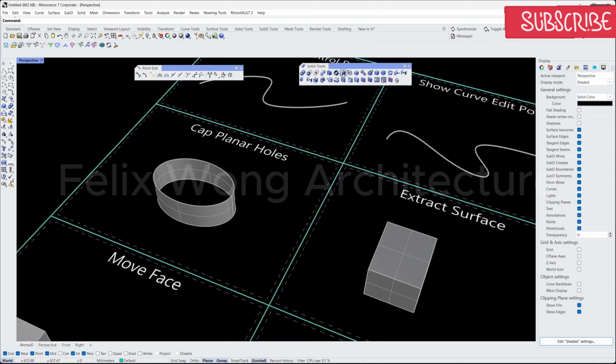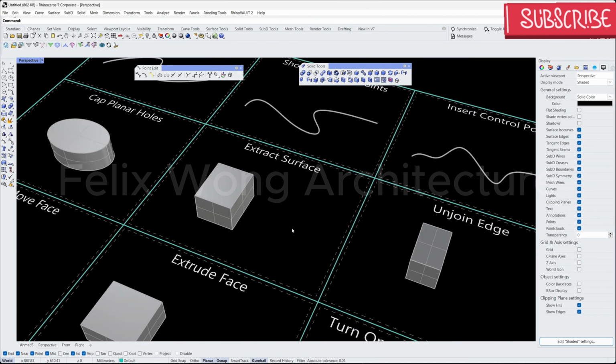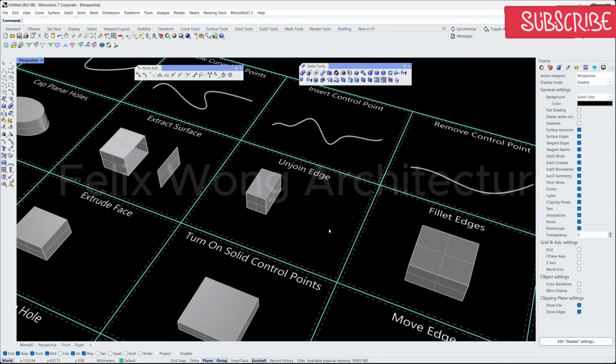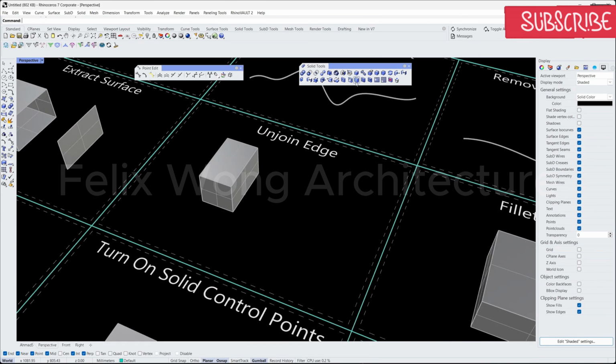Choose Cap Planar Holes to get a solid shape. To remove a surface from a shape, choose Extract Surface, select the face you want to extract, press Enter. To remove a poly surface from a shape, click on Unjoin Edge, select the edges of the poly surface, press Enter.